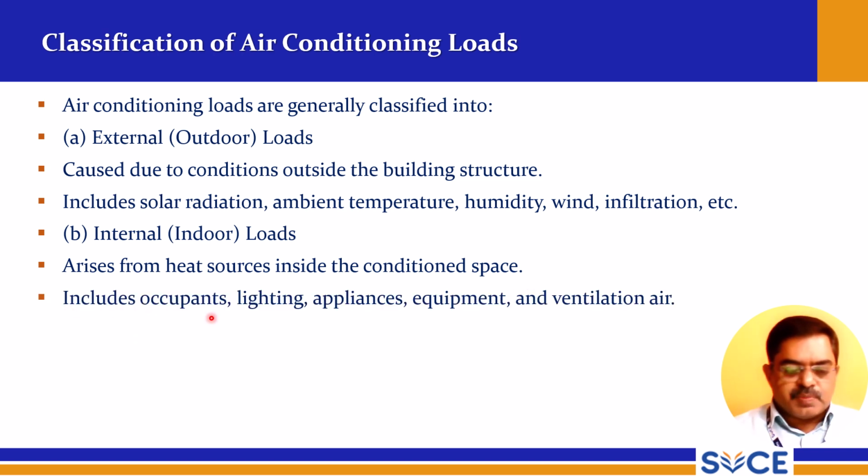It includes occupants, who are human beings sitting in that space, and lighting, which is also one of the causes. Appliances are different items inside the indoor space, plus equipment and ventilation air. Apart from this, every article we have inside a room or space will also cause load.